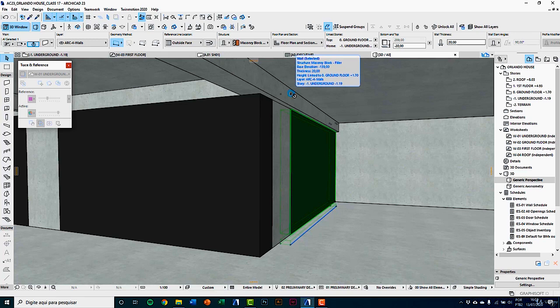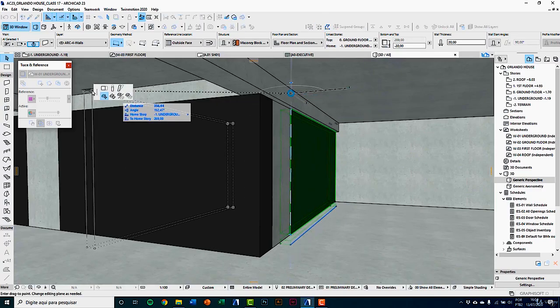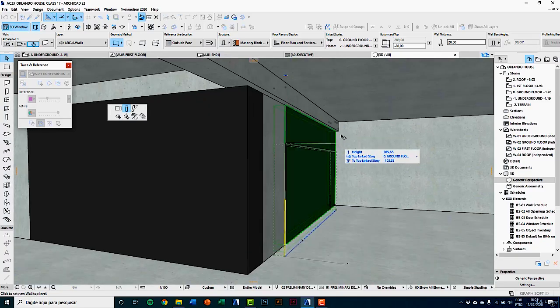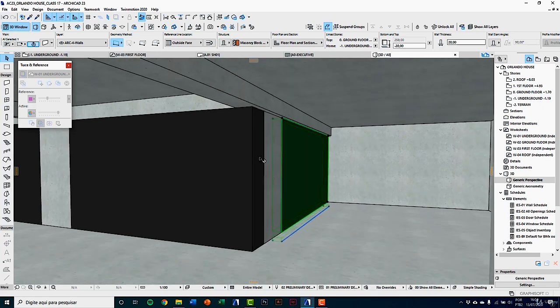And working with beam technology, we should model as right as possible to have correct sections, quantitatives, and so on. Clicking on Node, in the floating palette, choose Stretch Height. And here on 3D, I can click at the beam bottom face as reference. Now it's adjusted. I can do the same to other walls.